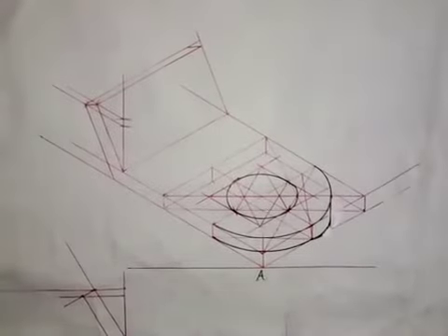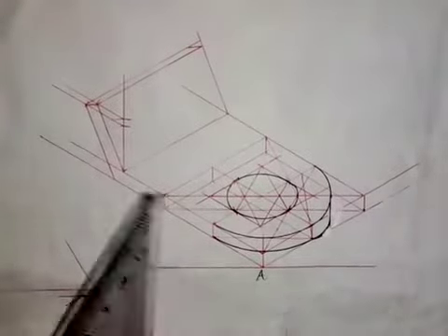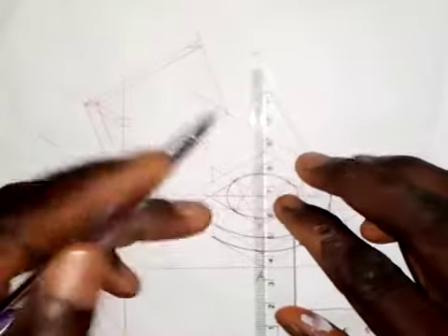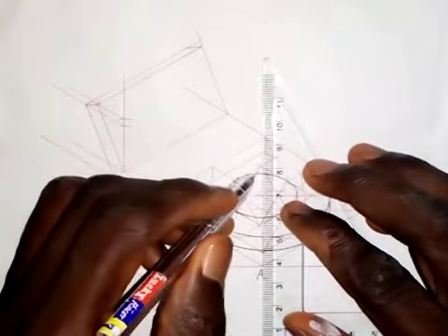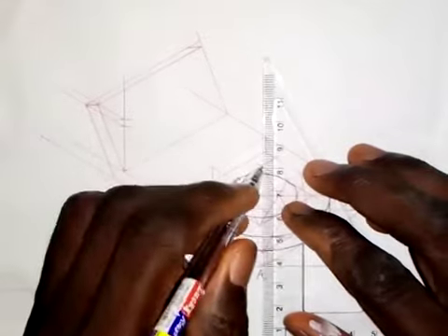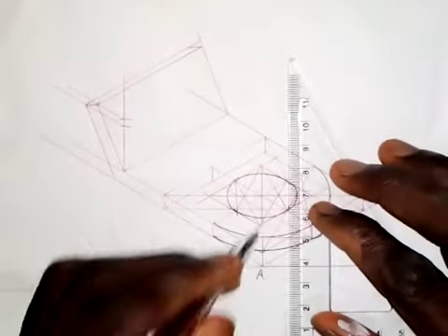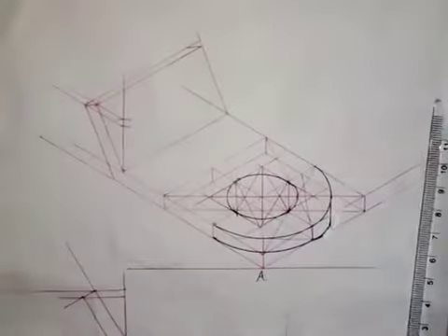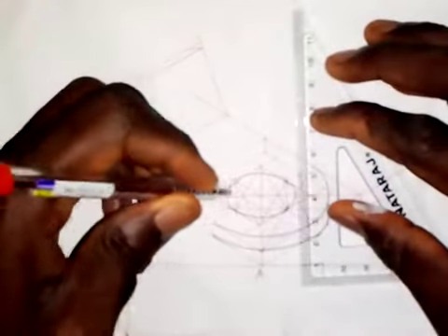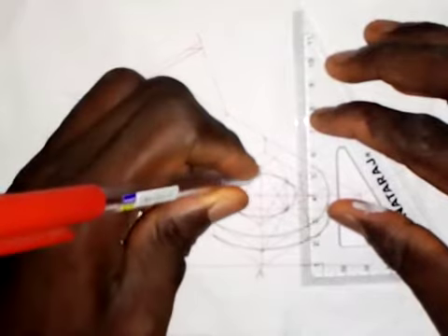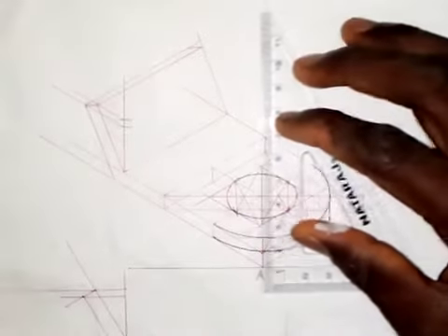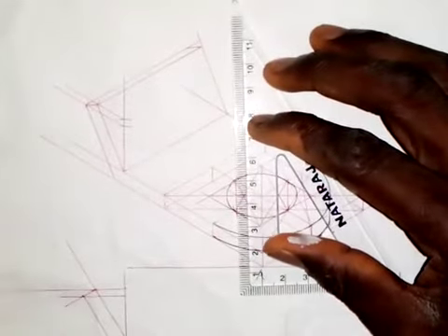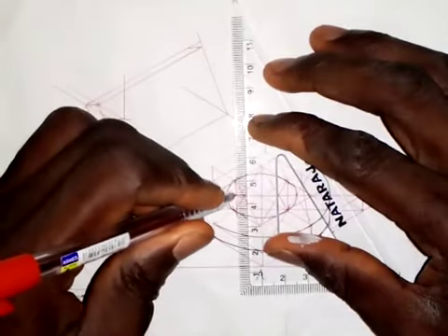So what you need to do to get that done is from this point here, draw a vertical line down like this. So from this point, draw a vertical line there, and from this point also, you draw a vertical line. So on this vertical line that we are drawing, from this point I will take a measurement of 6 millimeters. From here on the circle I will take 6 millimeters down. From this point I take 6 millimeters down. So what I mean is this, from this point take 6 millimeters down. So this is 6 millimeters already.